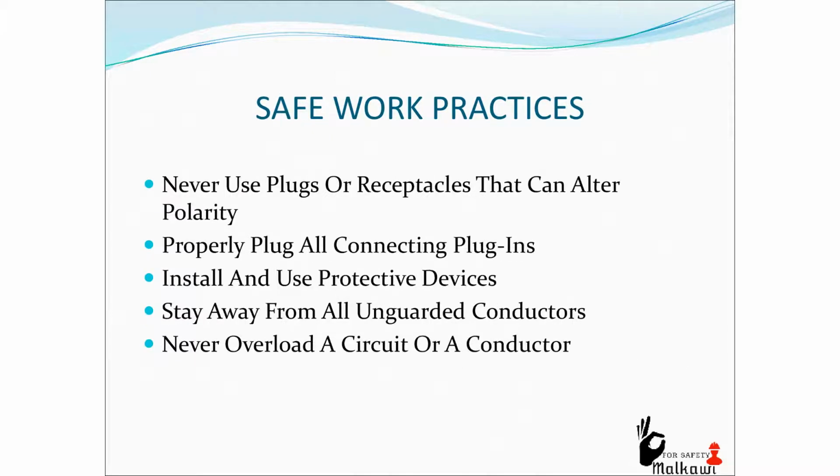Never use plugs or receptacles that can alter polarity. Properly plug all connecting plugins. Install and use protective devices. Stay away from all unguarded conductors. Never overload a circuit or a conductor.